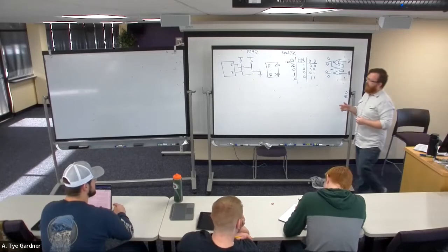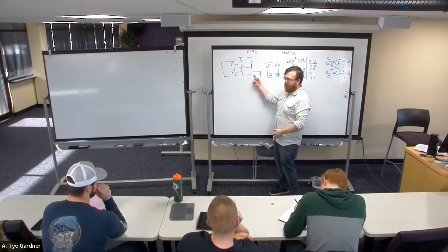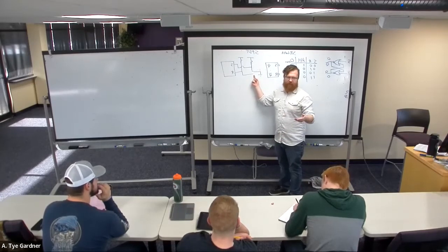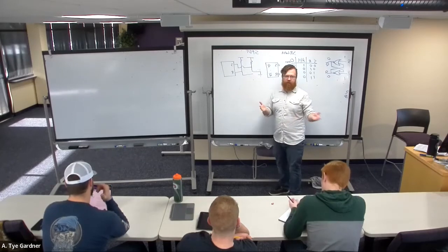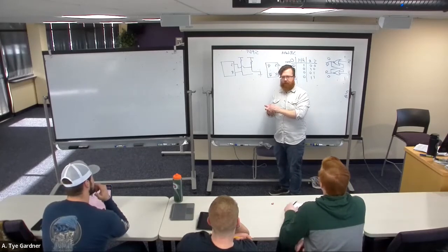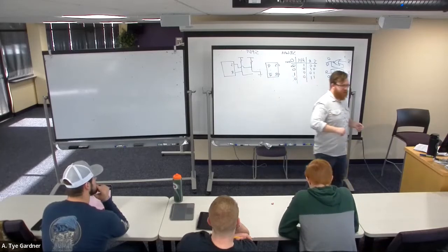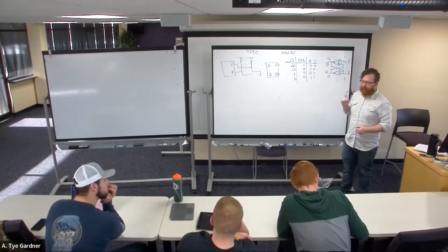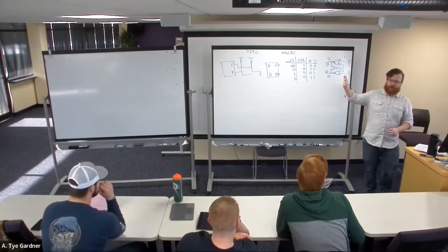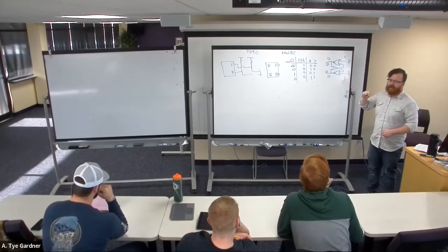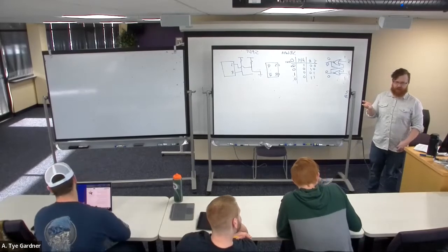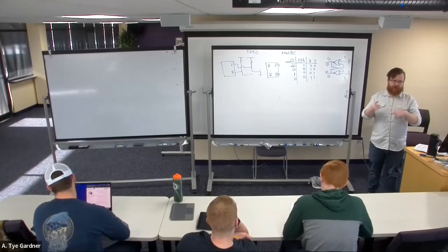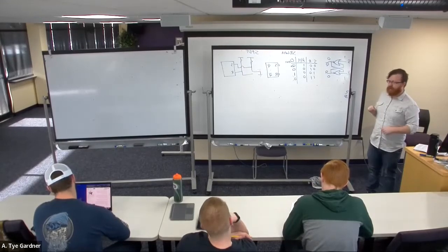Now this doesn't quite help us because now this is only going to track if I reset it manually, right? Because once I've set it, it's going to say 1. So if I want to reset the count, then I have to intentionally go back to R, which is going to do the same thing, which is going to go reset, and just go 0, 0, 0. But the bounce of the switch no longer is going to toggle on and off like our initial design would have. So we're going to build up an even bigger, more complicated circuit slowly that's going to get us to debouncing a switch, which is going to be like, what if we really do just want to count it go on and then off, and we just want it to release? And that's where we're going to slowly build towards with these devices.